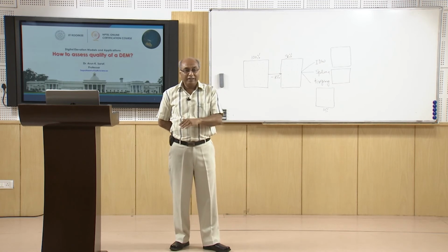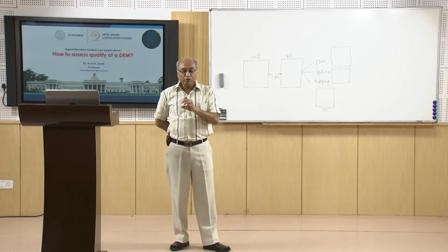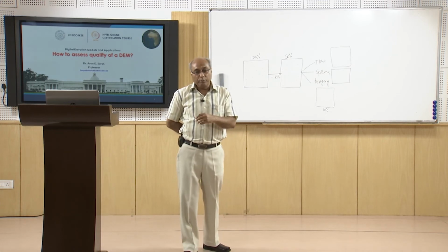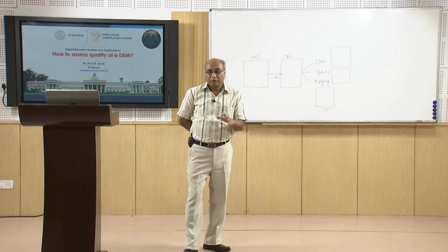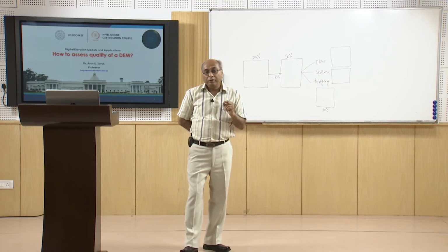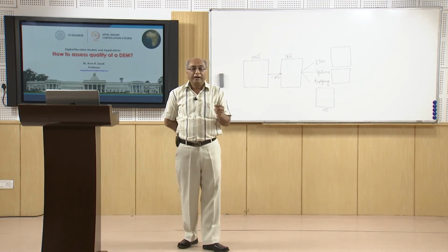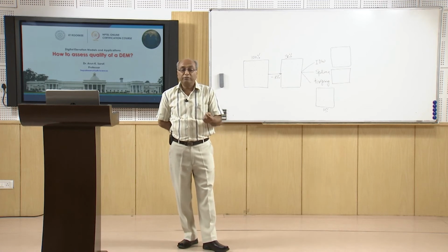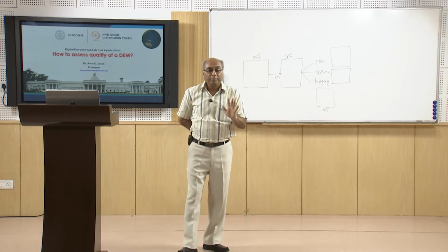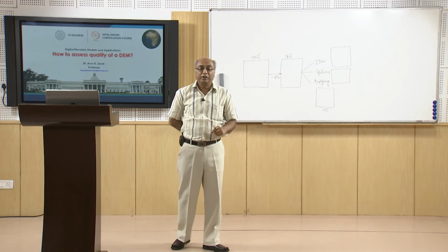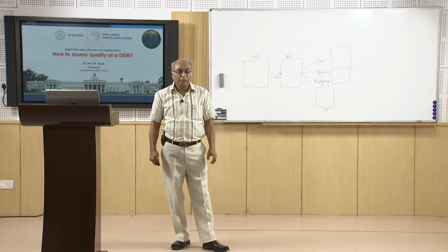So here the source scale of the point heights from a topo sheet will matter most. So one has to take care about this aspect as well. For medium or coarser resolution data, corresponding point heights coming from 50,000 scale may be good, but for higher spatial resolution data, GCPs coming from 50,000 scale may not be good. So one has to remember.